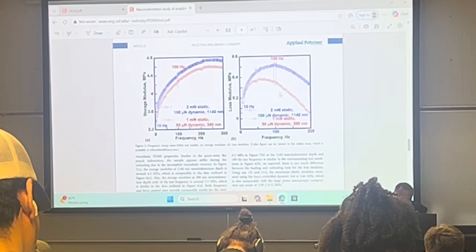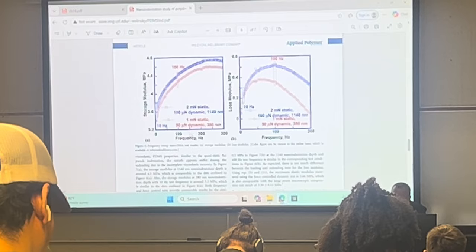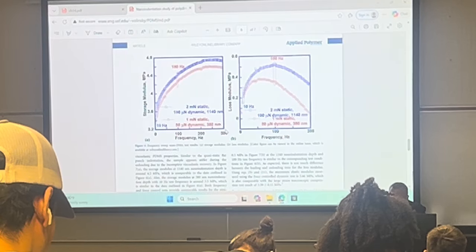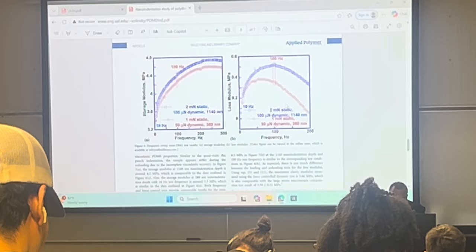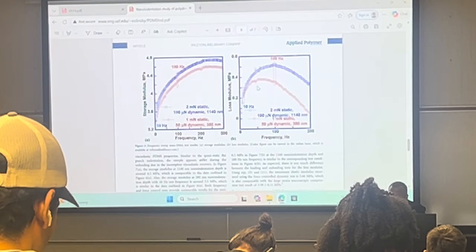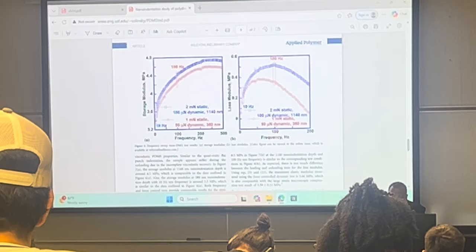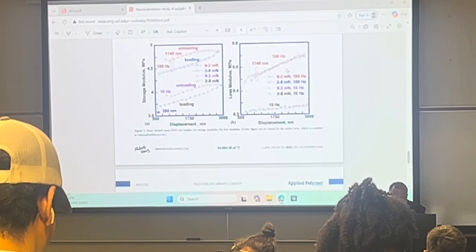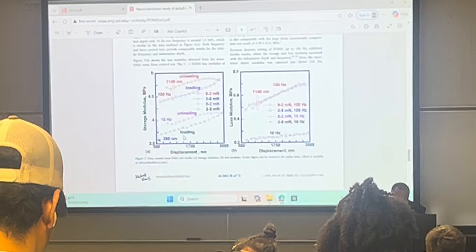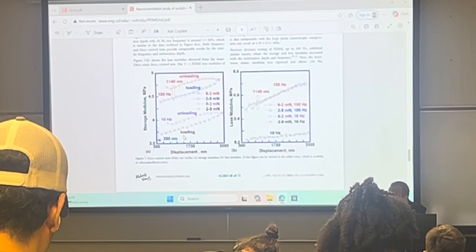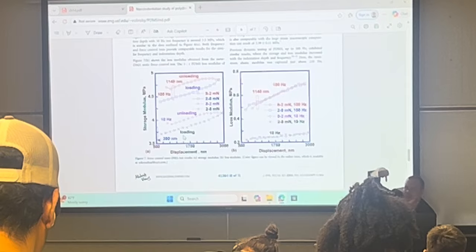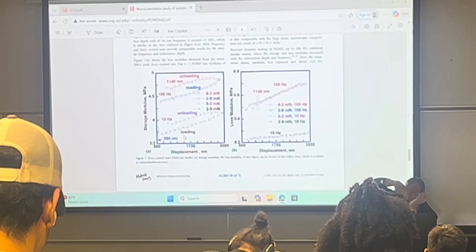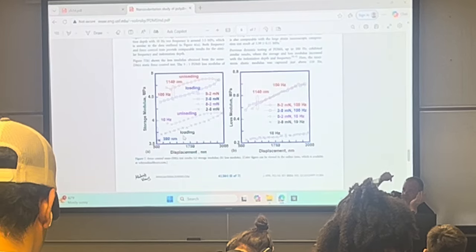And what you see here is the storage modulus as a function of the frequency in hertz, from 0 to 300 hertz. And this is the loss modulus that deals with the part at 100 hertz. The reason I outline 100 hertz here is because we've done this in terms of the oscillation. So the way you bring this tip down, it's in contact, this cylindrical punch, and you start to oscillate it.